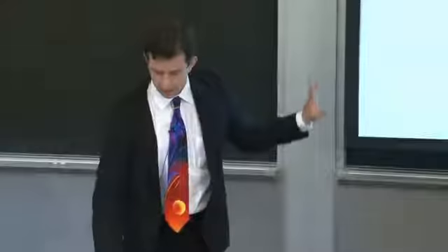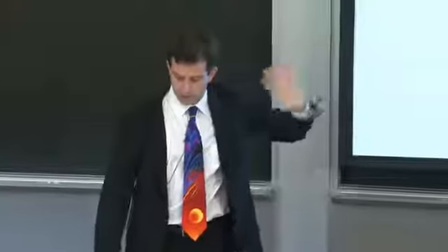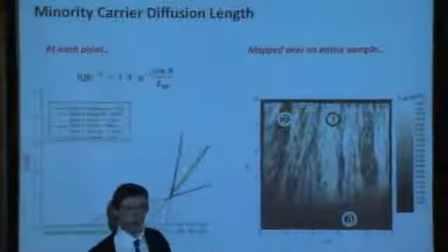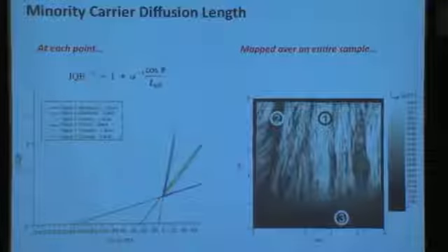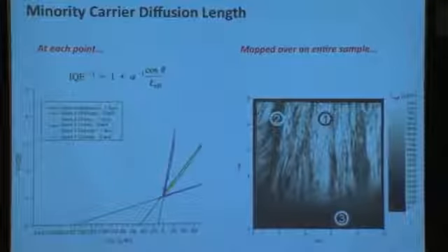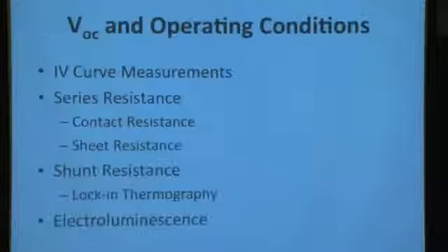Small aside, small footnote there. OK, important: minority carrier diffusion length. That's of utmost importance. So we can relate the diffusion length directly back to our IV curve via the saturation current, via the J naught, or I naught, depending on whether you're looking at density or absolute amount.